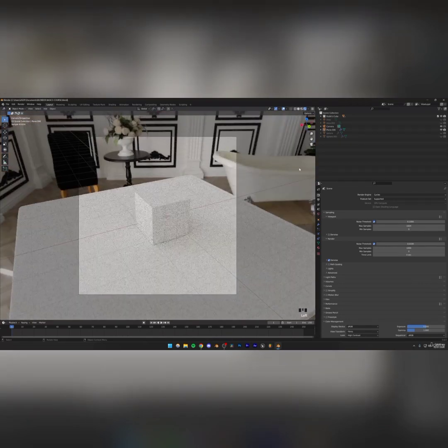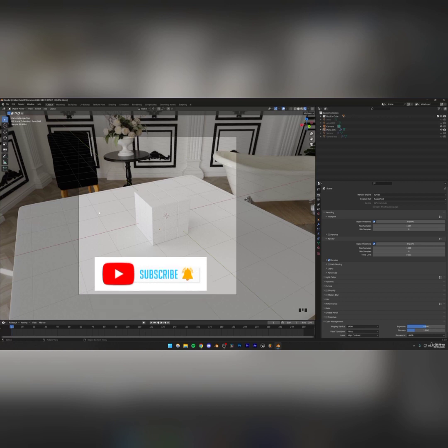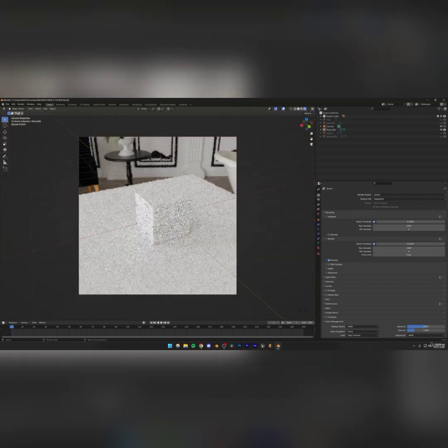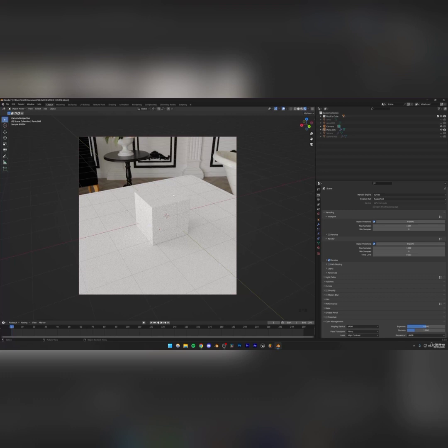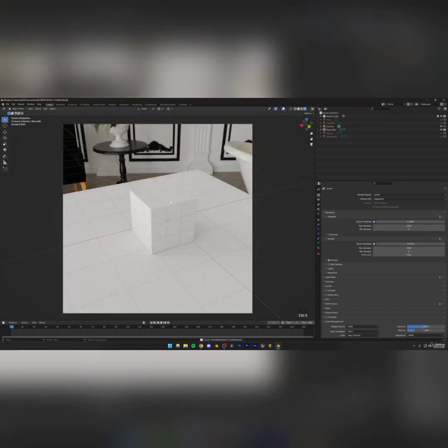So I'm just going to go inside my camera, and right now you're going to see that even though our camera is right here, everything outside of our camera is also rendering. If you want to render only what is inside your camera, by the way, the reason you would want to do this is so that you can save some performance and actually look at how your camera is going to look, right? So you can press Ctrl B on your keyboard, and then highlight this area of your camera, and it's going to automatically snap to the camera only, right? And so I'm just going to press Ctrl S. And so now we can go ahead and start to add the textures, right? Our lighting is essentially just done. It was just as simple as that.